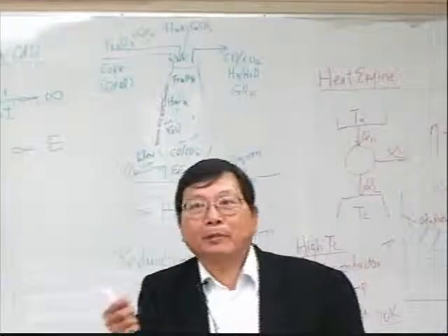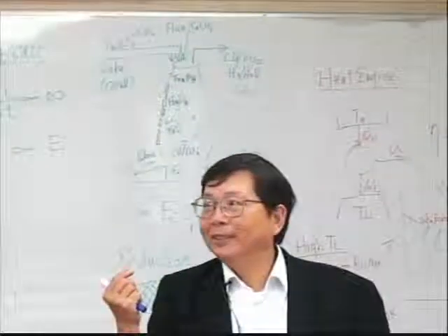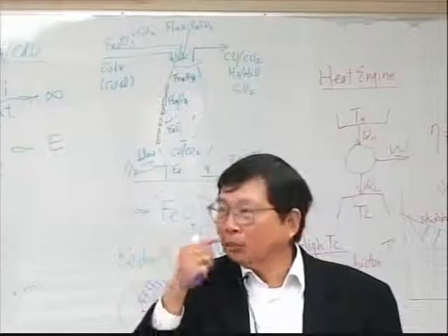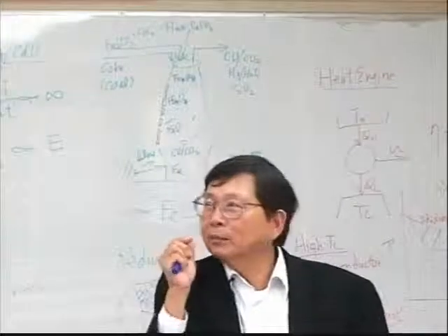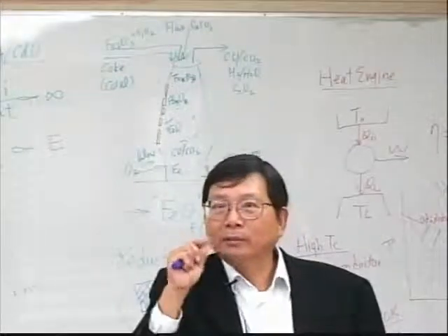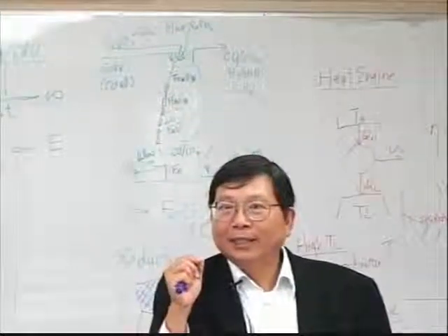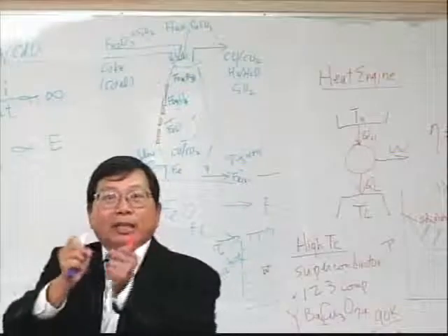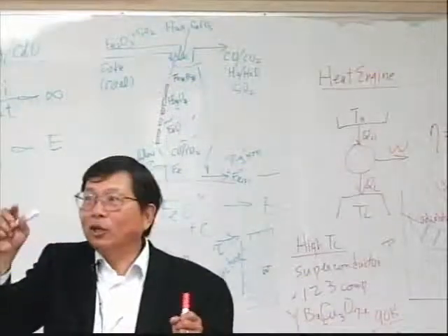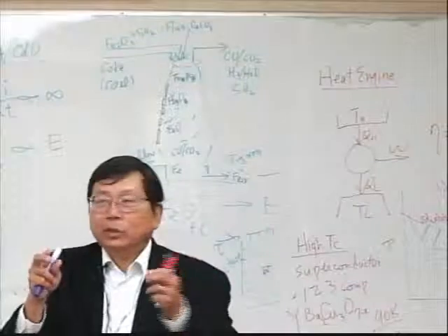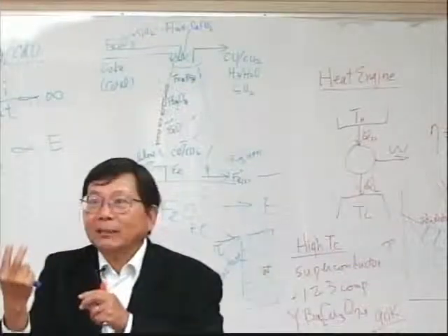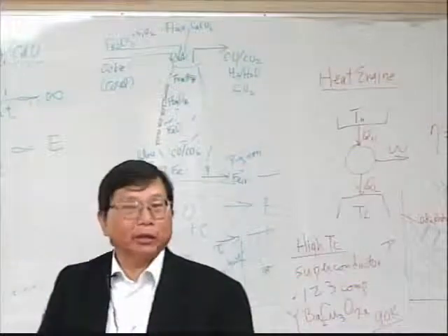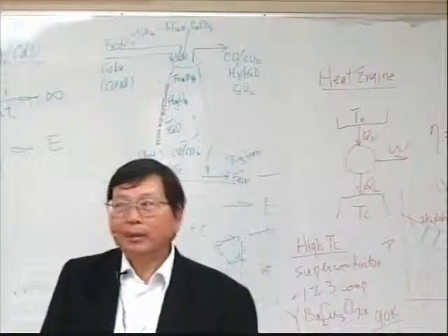That's the way people do sputter deposition using plasma, very localized. So sometimes you can smell some odor, because when you break the air, oxygen becomes O, and atomic oxygen attached to diatomic oxygen gives you O3. So sometimes you smell ozone next to it.